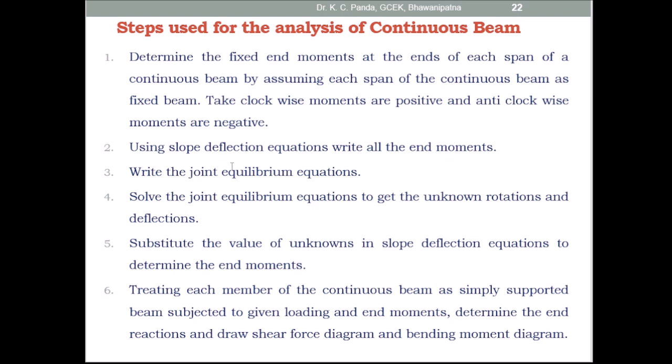Then by using the slope deflection equations, write all the end moments. Then write the joint equilibrium equations. Then solve the joint equilibrium equations to get the unknown rotations and deflections. Then substitute the values of the unknowns in the slope deflection equation to determine the end moments. Then treating each member of a continuous beam as a simply supported beam subjected to the given loading and end moments, determine the end reactions.